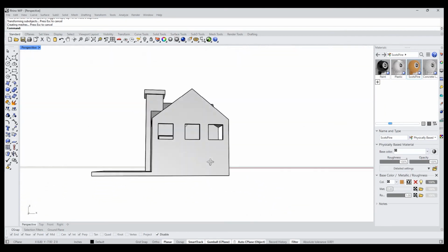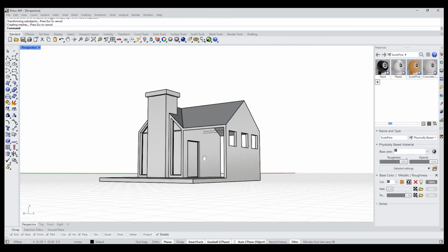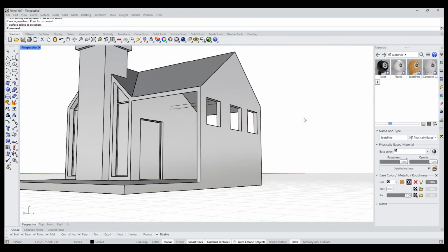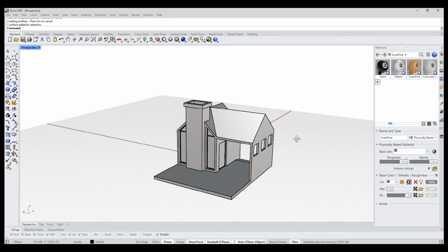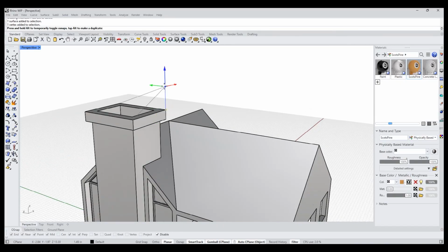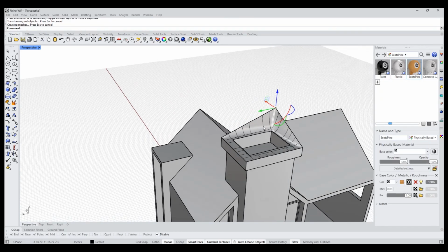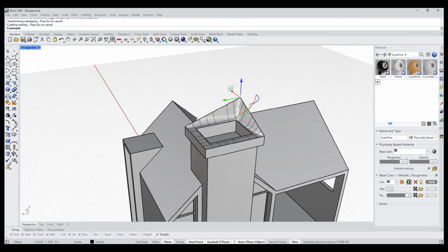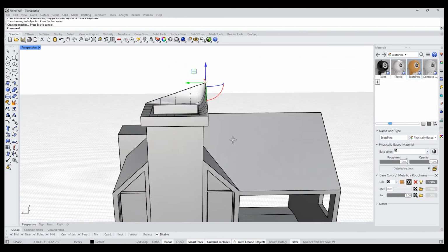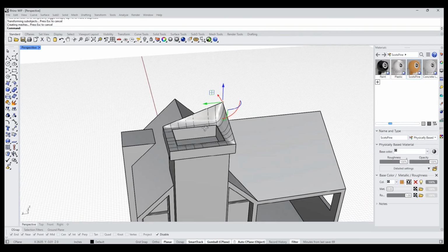That's the key, is anytime you force the geometry to go from degree 1, which is flat, to anything that's got a curve to it. If I grab this point, for instance, and I pull this up, that has to curve. Anytime you force that to go from degree 1 to degree 3 geometry is where you're going to run into an issue where you're going to get this weird rebuild. And so on one hand, you could say, oh, well, that's annoying that it does that. But on the other hand, it is pointing out an issue with your model, right? It's pointing out, especially for something like this that needs to remain planar, an issue that you need to go back and actually try and figure out why that happened and just repair it.